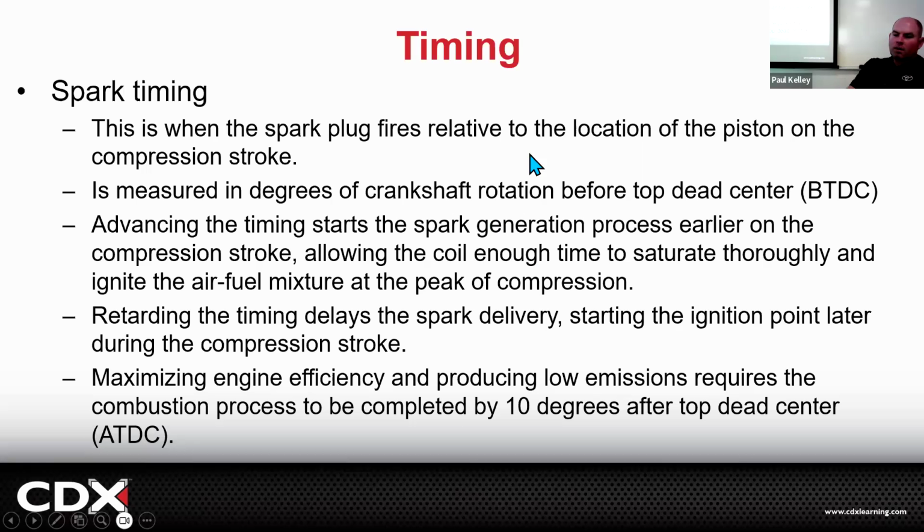Cool. So again, when we talk about retarding the timing, these aren't my terms. These are the terms. You can take them or you can leave them. Just wait till you do manual transmissions and you talk about clutch parts. All right, but advancing the timing means it's early. Retarding the timing means it's late. That's it. It's that simple. It's not that the timing has a low IQ. It's simply that the timing is late. It's behind schedule. It's supposed to be at 10 degrees before TDC, but instead it's only at 2 degrees before TDC. It's late to the party.